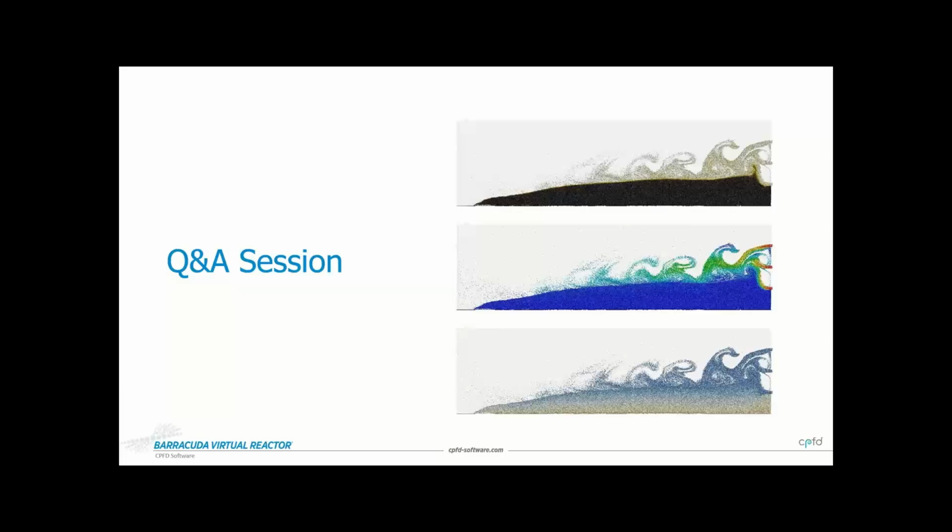I have two questions here that might be getting at the same thing from different askers. One says, does the model account for different shaped particles? And another says, is the proppant's sphericity important? Spot on, and I think they're both related. The way we account for the particle shape is through that specification of the sphericity, and then using a drag model which is more appropriate for non-spherical particles. That's how you would account for that.